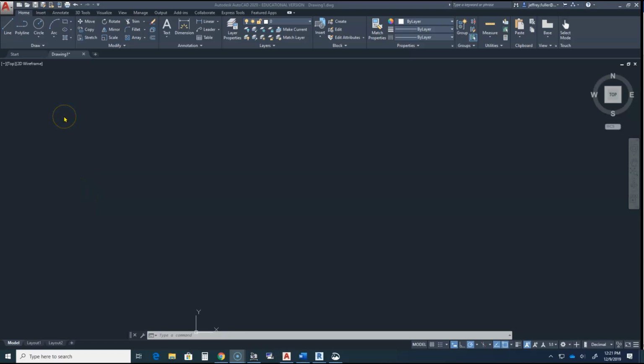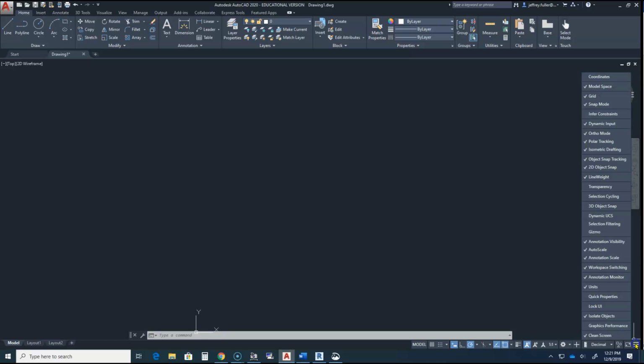The first thing we need to do is check to see if your dynamic input is on. Mouse to the bottom right of the screen and look for this icon: 3 horizontal lines stacked vertically one on top of the other. Click the icon to reveal a menu. Look for the term Dynamic Input and click on it.